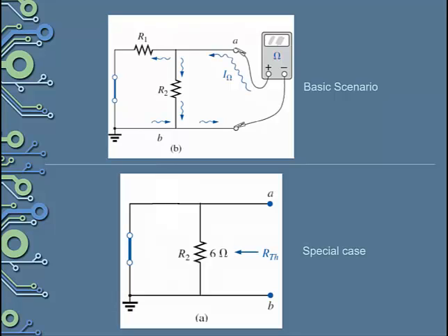This is the same as normal, where you would use rules such as Ohm's law to determine the resistance, but in this case, it is to be done from the perspective of the removed component between A and B, which is different from doing it in relation to the voltage source. Care must be taken in this step, however, as in some cases, the voltage source being set to a short circuit will make a resistor in parallel redundant and will therefore bypass it, changing the total Thevenin resistance.